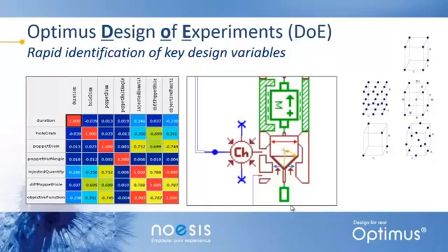On the right is a picture. This is a 1D package simulating a diesel fuel injector valve. Design variables in this case were some diameters, which you'll see in blue and red, and a poppet half angle, which is the yellow, which is that little triangular section.